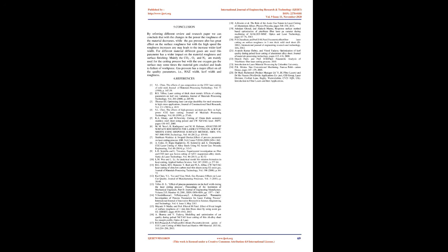Mainly CO2, O2, and N2 are used for the cutting process, but with the use of oxygen gas, the material sometimes gets cracked, which leads to failure of the workpiece. Gas pressure has a major effect on all the quality parameters, i.e., HAZ width, kerf width, and roughness.